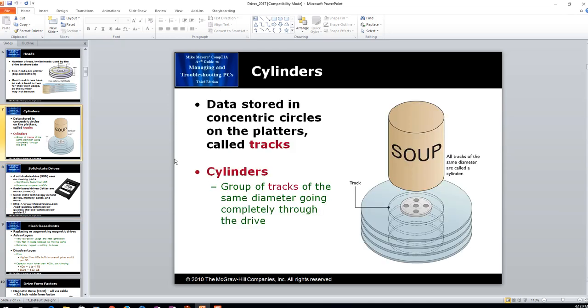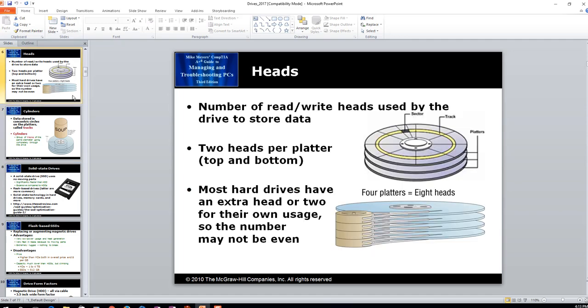If you look at this disk here, this is spinning. Let's actually go to this picture. This disk is spinning, the head is going back and forth. So if the hard drive wants to access a very specific bit, it first has to position the head onto one of the tracks, and that does take a little bit of time to shift that head back and forth. It's pretty quick, but it takes a little bit of time. And then also the disc, even though it's spinning at maybe 5,400 revolutions per minute, it does take a little bit of time to actually, if this is the sector we're looking for, and the head is over here, that has to spin all the way over there to get to that head.